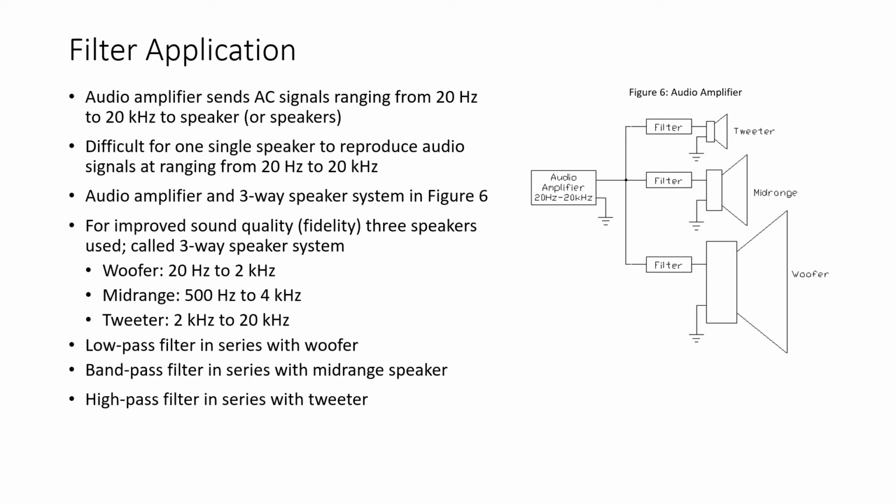And of course, we need a high pass filter in series with the tweeter to allow only frequencies above 2 kHz to pass to the tweeter. So this is an example of an application for filters.